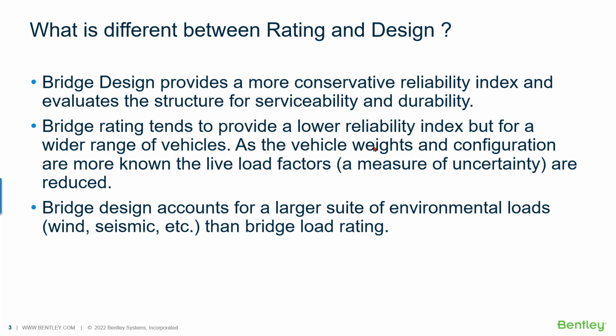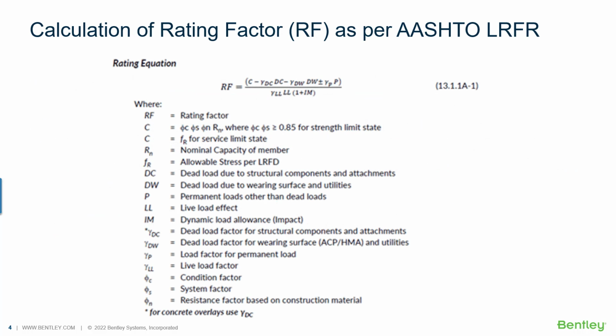Finally, for bridge design, we take a larger suite of environmental loads, for instance wind, seismic, all that kind of thing, that we don't take into account for bridge load rating, as we think that this crossing of the bridge will not be in such an environment. If we take in the LRFR the equation for the rating factor, we get that huge equation. But in that huge equation, if you look closely, it's mainly a simple one with a lot of different coefficients.